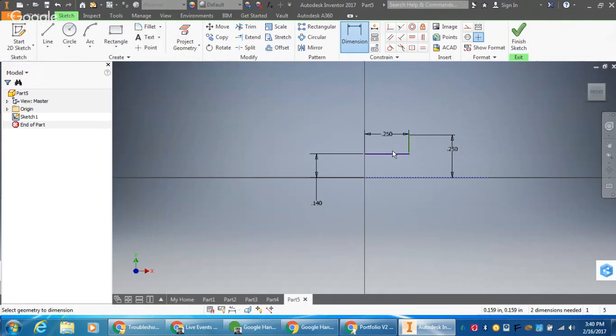And so that's good. So here's the starting point of our shape. Again, I can move some of this stuff around so you can actually see what's going on. All I have is 2 lines here defining the bottom corner. The next thing I want to know is this next line here. I'm going to just click and hit escape here. I can show you another way to do this. I can start at the center, and I know all the way up to the top of the curved edge of the wheel, there's a little center point there. And that little center point there is 1 from the center point. So I can just click 1, enter.